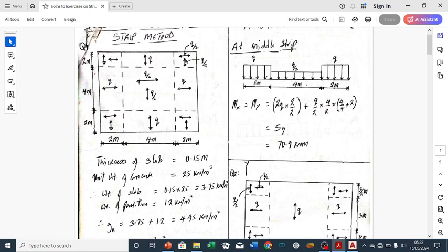So first of all, we change it to a point load. If you multiply this Q by 2, this is how we have this 2Q here. When you multiply it, you're going to place it at the middle of the span of the load. By placing it at the middle, the distance from that middle to this edge is going to be this 2 multiplied by 2. So that's why you have multiplied by 2 over 2. So this bracket takes care of the moment due to this load Q.